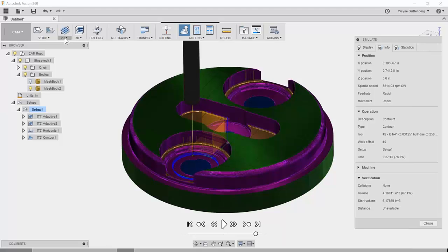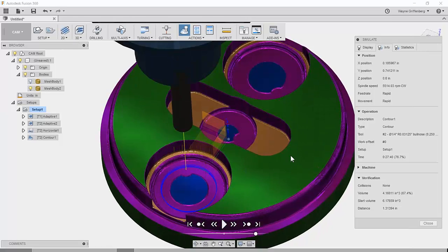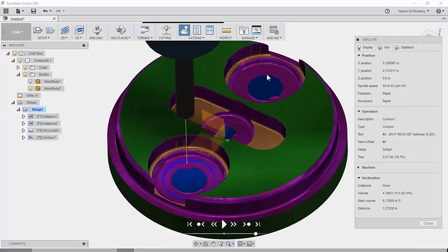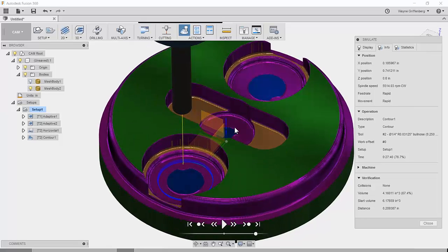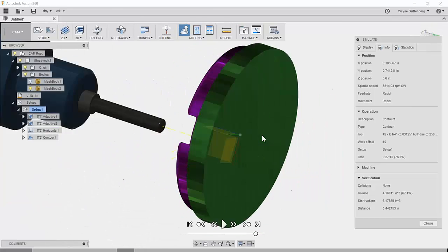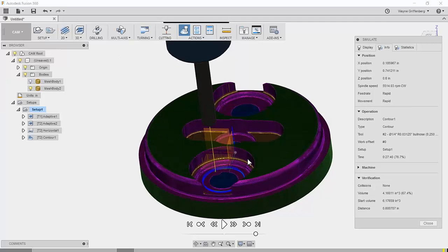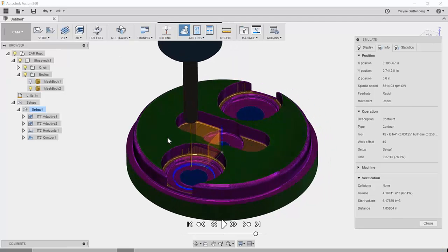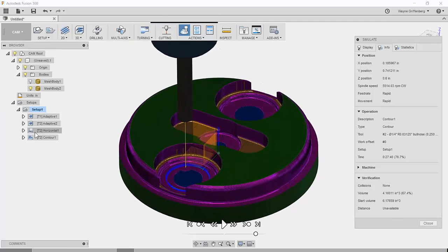Okay, so as we're here, another step I'd like to show you is this looks pretty good. So I was able to get this simulation done. I can see it's going to work for me. That's what they're going to get on the results of this first operation. What I want to do is flip the part over to do the other side. I'd like to use this result as the stock going into the other side of the part as op2.